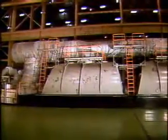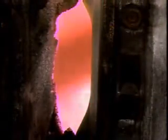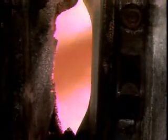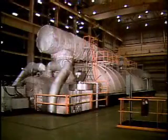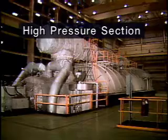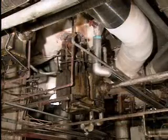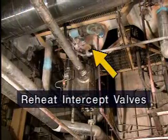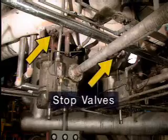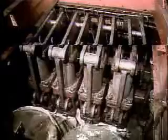The steam in the turbine gives up some of its heat as it passes from one stage to the next. For this reason, it's often necessary to return steam to the boiler for reheating before it passes through the entire turbine. This reheating most often occurs between the high-pressure section and the intermediate pressure section. Reheated steam is returned to the turbine through reheat stop valves and intercept valves. These valves, along with the stop valves and the control valves, also provide protection for the turbine.